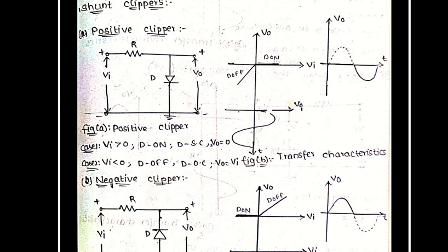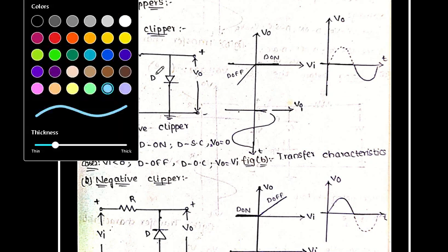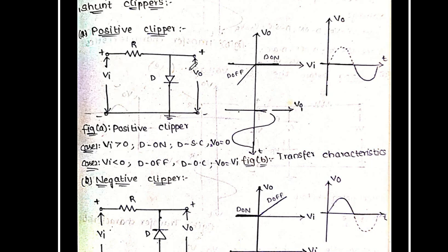That 2 volts is applied to the anode of the diode. It is clearly observed that the cathode of the diode is connected to the ground. That means the voltage at the cathode of the diode is 0 volts. The voltage at the anode of the diode is 2 volts. That means the anode has a greater voltage compared with the cathode.